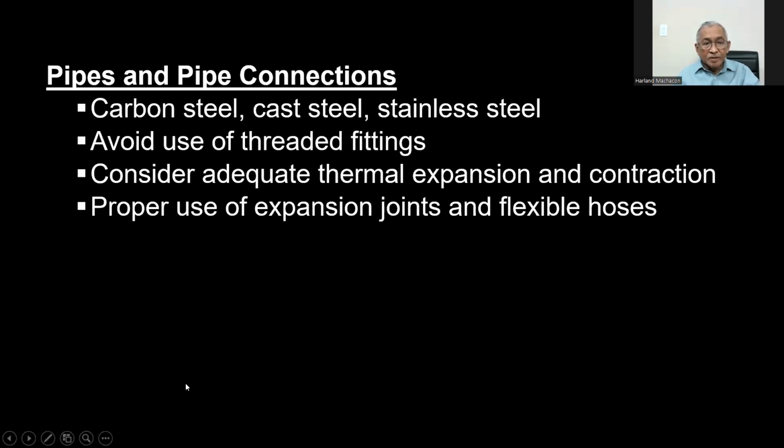Pipes and pipe connections. The pipes may be carbon steel, cast steel, or stainless steel. Avoid use of threaded fittings. Consider adequate thermal expansion and contraction. And of course, the proper use of expansion joints and flexible hoses is very important.